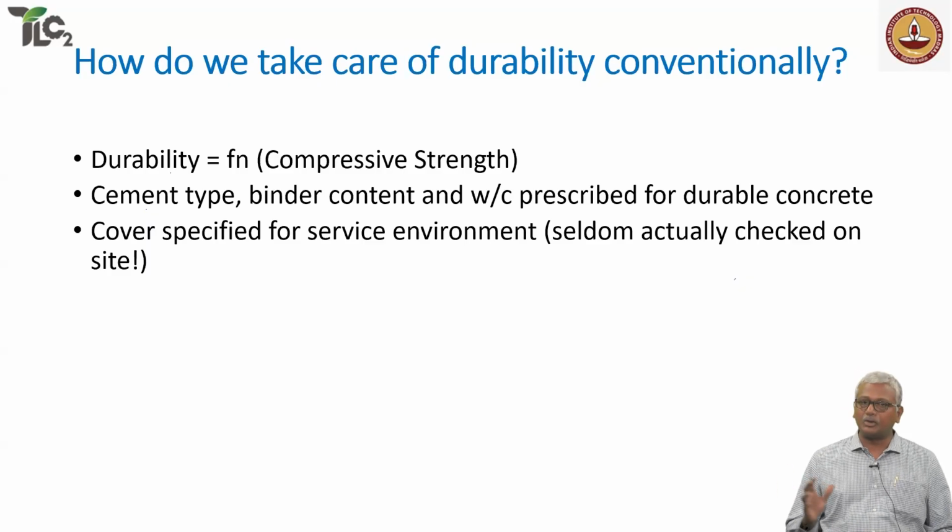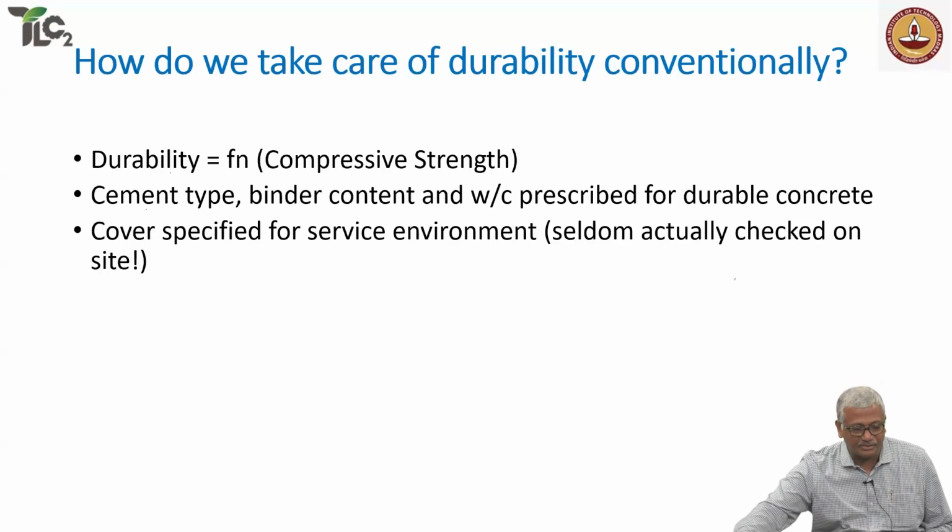We do an inspection that the cover blocks are placed properly. That's about it. But even there, a lot of issues are lacking. People don't really inspect well enough to see whether the cover blocks are in place, whether they've been tied properly, whether they are in danger of actually moving, reducing the cover and so on and so forth. So all of those things are not carefully assessed on site.